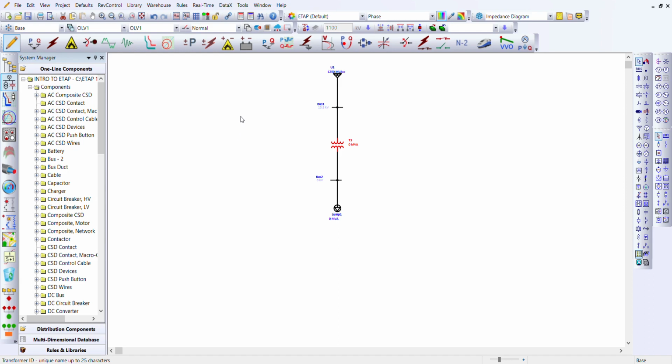Now coming down to the transformer, the rating of the transformer. Watch now, this primary of the transformer is connected to bus 1, and bus 1 initially has a rating of 13.8 kV, and that is why it is here, primary bus 1, 13.8 kV already. Then let's go to the main rating of the transformer, MVA, as the apparent power. Let's say about 20 MVA. And let's go to the impedance. If you notice here, the secondary is 0. That's because the bus it is connected to from beneath, I have not actually put the nominal kV. Once we put it, it will reflect here.